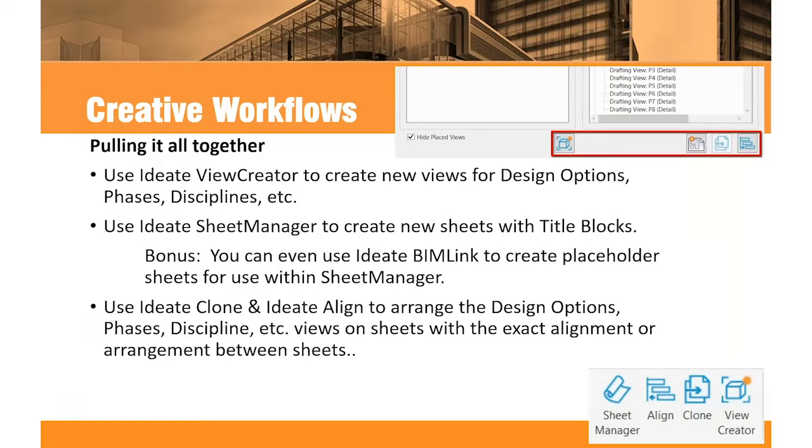So again, you can use all the tools together to first either create the views and then use the sheet manager, the align, and the clone to create multiple sheets that all match the alignment.